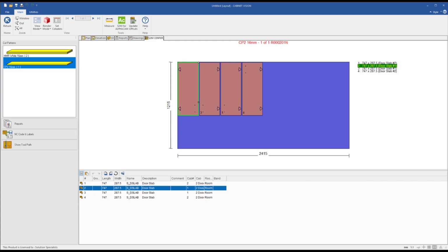As you can see on this sheet, I have 4 doors. They're all stacked along the top, because that is normally what I would want them to do. However, for this sheet, I may decide that I want to do the opposite, as I know I have a job coming up, and having the shorter square offcut is going to be more convenient than the longer rectangle. To do this, I'll need to rotate all my parts by 90 degrees, and move them into a new position.